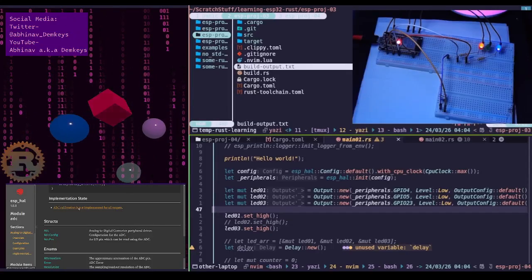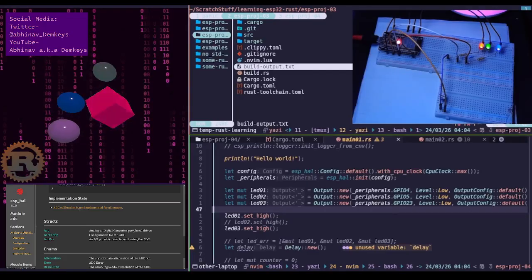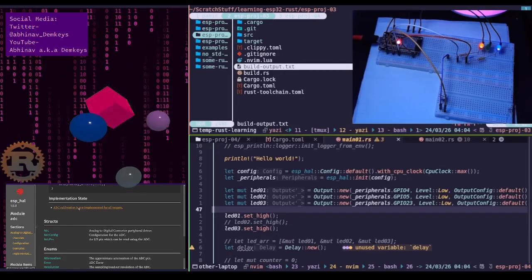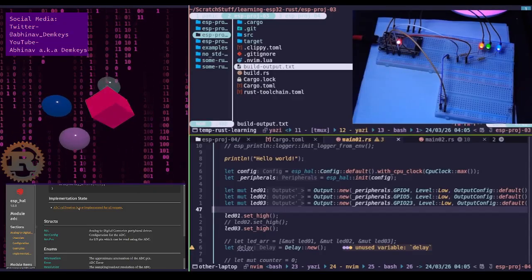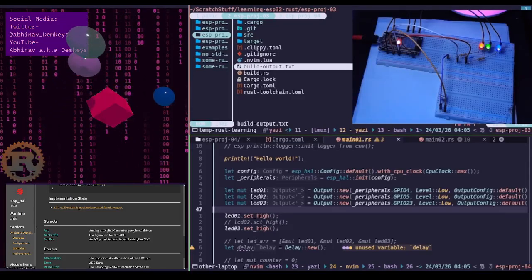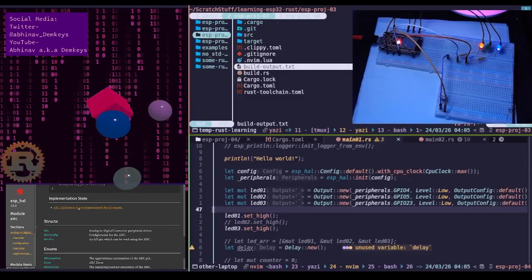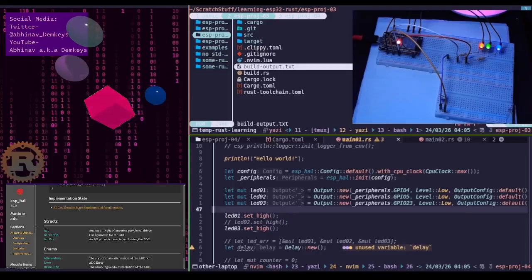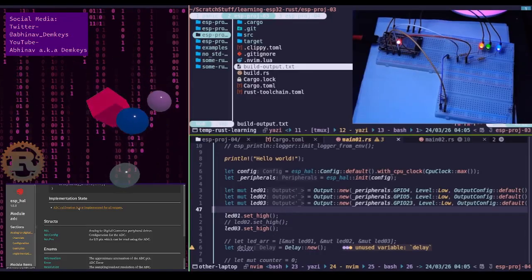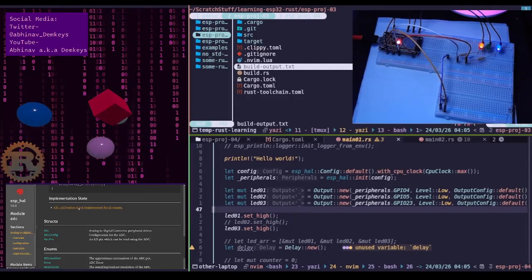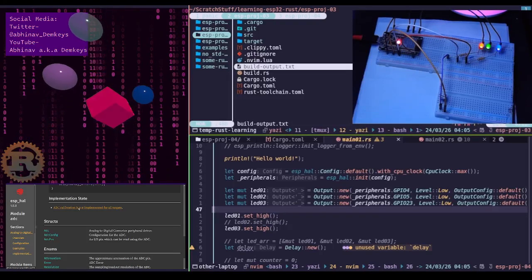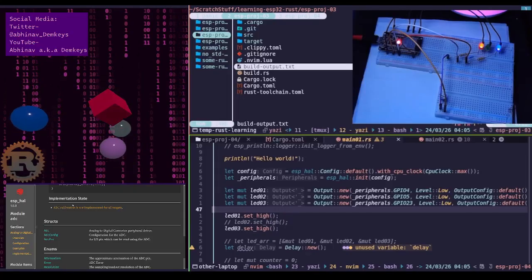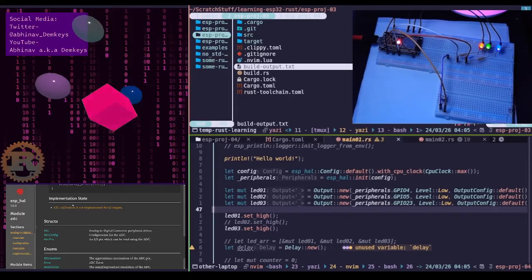Okay, a quick tip for better accuracy. Even without software calibration, you can significantly improve your results by using multi-sampling. Since the ESP32 ADC is a bit noisy, taking 10 to 20 readings in a row and averaging them will give you a much more stable, though still uncalibrated, value. Okay, that's a good idea. Multi-sampling.